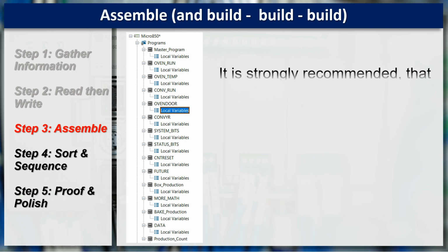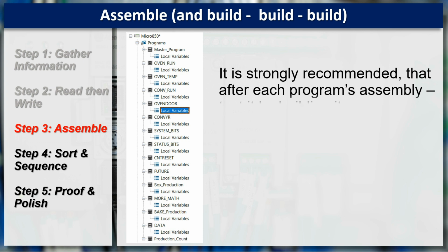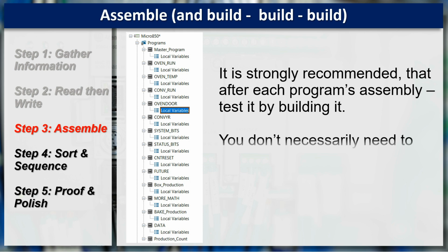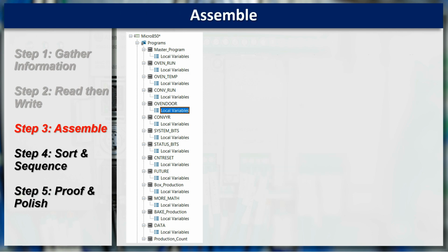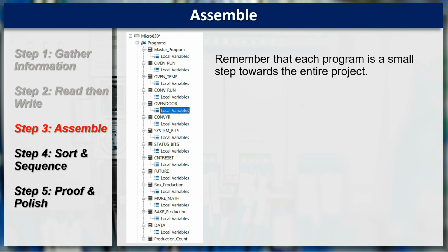It is strongly recommended that after each program's assembly, test it by building it. You don't necessarily need to download and run it, but the build utility will identify potential problems or typos. Remember that each program is a small step towards the entire project.